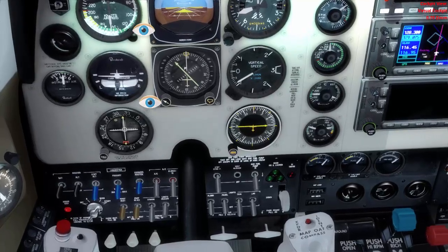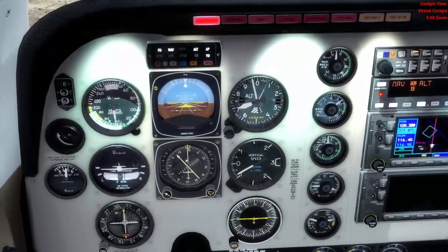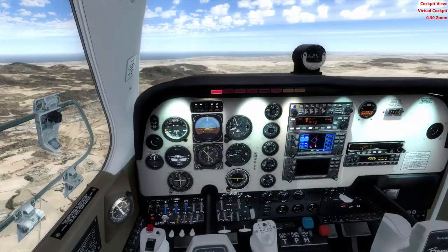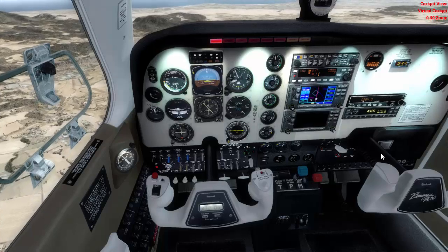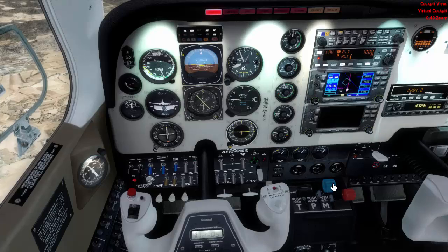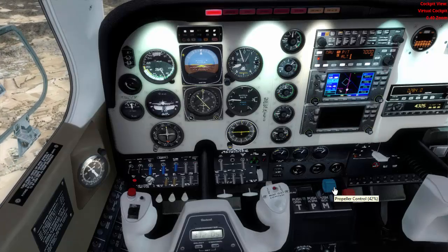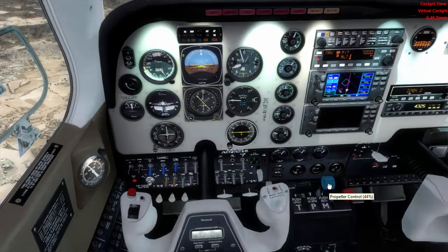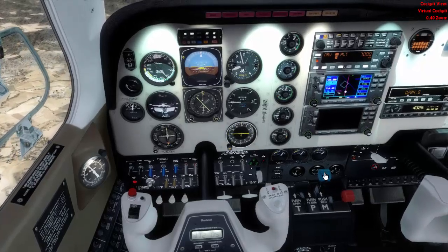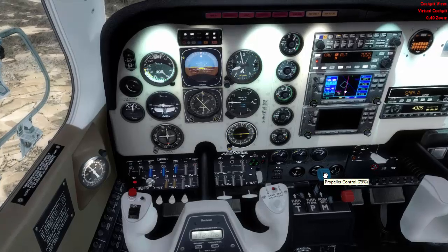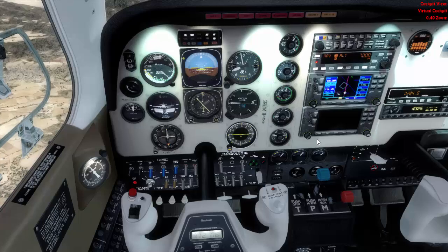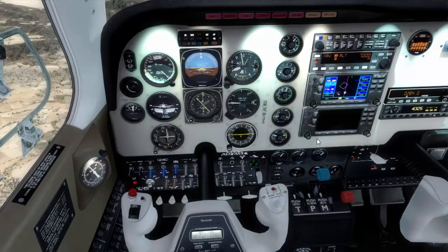There we are flying at 140 knots, and what we will do right now is reduce the cruise power settings to reach more or less the recommended cruise power settings in our cruise performance tables that we were taking a look at, and perhaps we will consult them again, okay? But remember our recommended power settings, okay? Recommended, not compulsory. So you can follow those power settings if you want, okay? You are not forced to, okay?